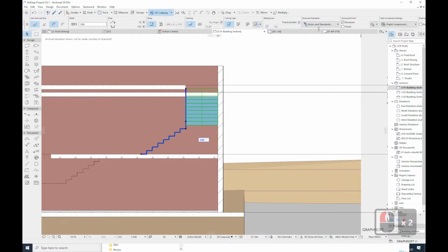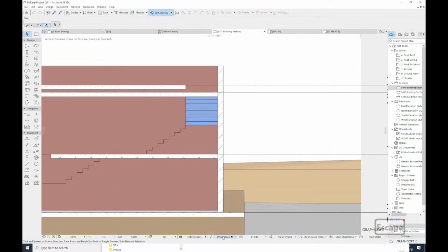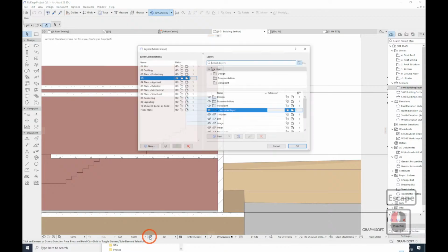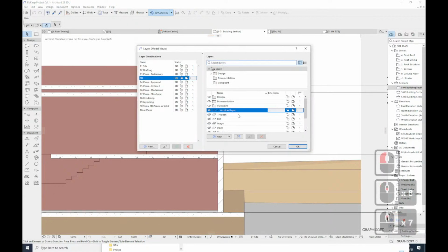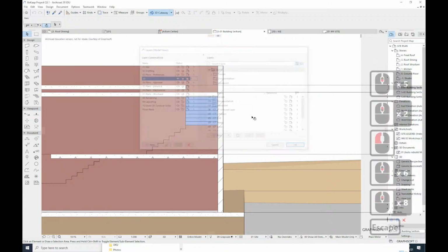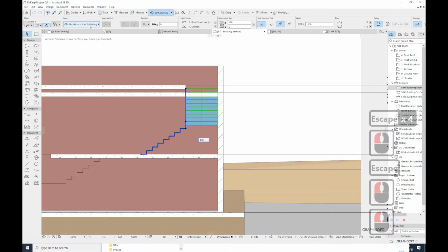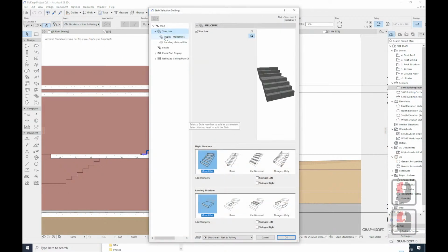You know what? Let's put it on a layer. If you go to layers, I'll explain. It's on a layer that you can't see. That's where the problem is. Where's site? If we go to your layer combinations, in 3D you need to make sure some stuff is hidden. I did go through that as well. Go to design, and let me make sure the structure stuff is right. These things each get put in their own layer.